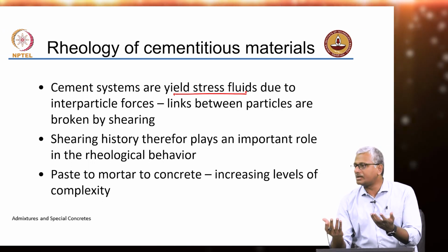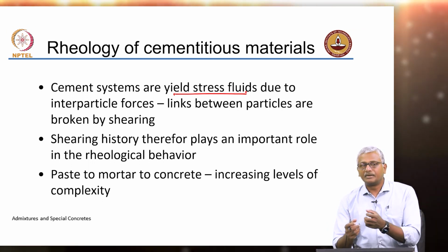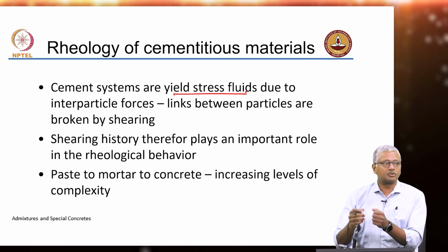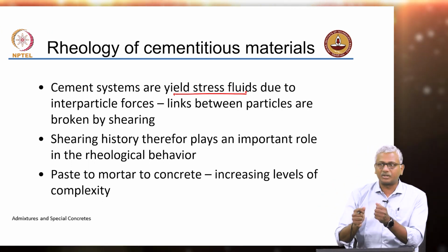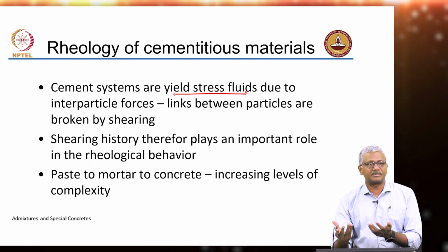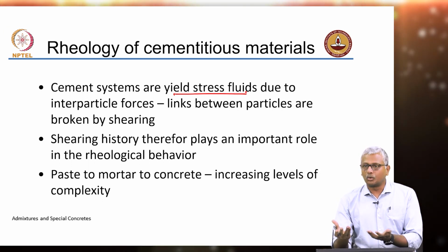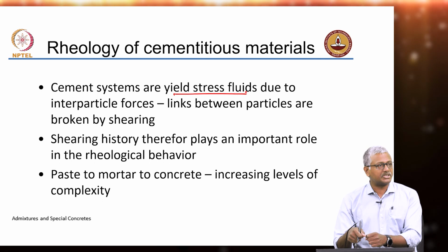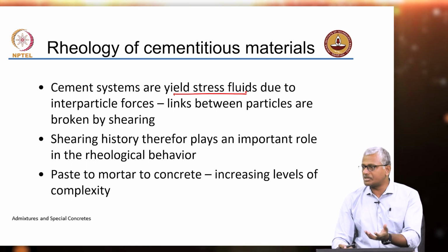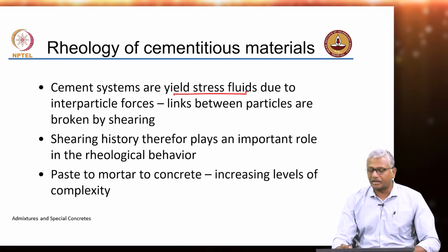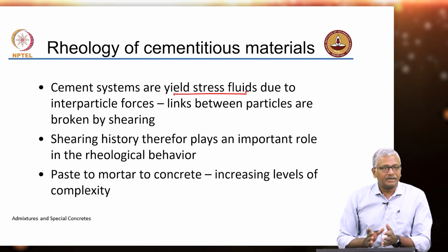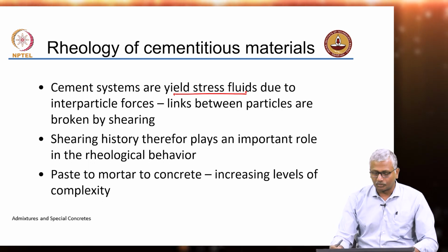So, imagine concrete. Concrete has a lot of coarse aggregate. Coarse aggregate has intergranular friction. Now, if you change the design so that you put in more mortar between the coarse aggregate, you are going to reduce that friction. It's going to flow better, right? That's what's happening in this case. But when you don't do that, and when you apply vibration, that vibration allows the particles to start moving past each other. Okay, so that vibration does the job of overcoming the interparticle forces to cause the breakage of these interparticle forces, and you shear the material to start to make it flow.